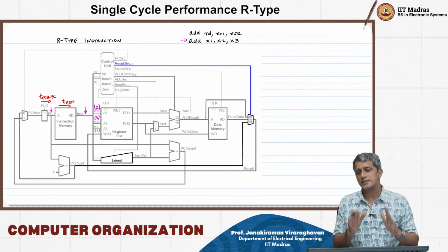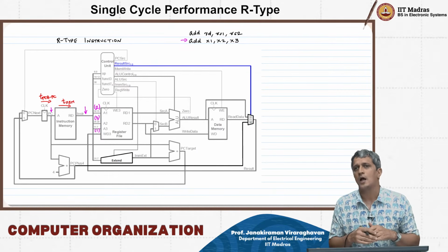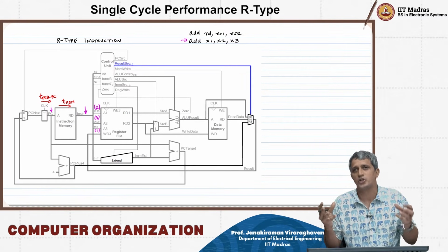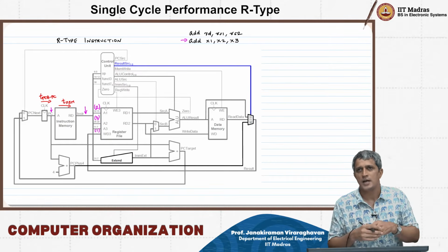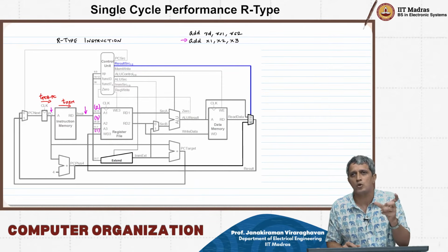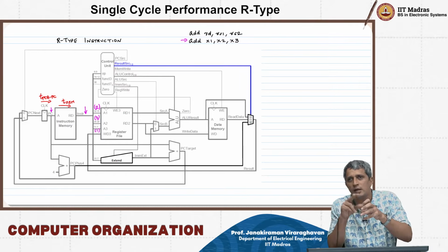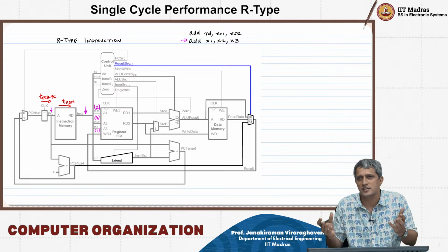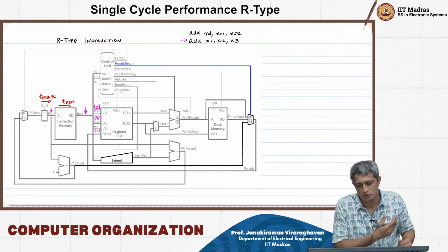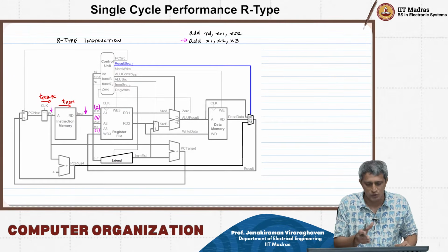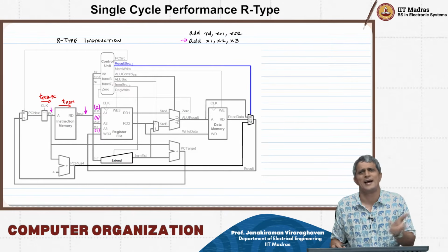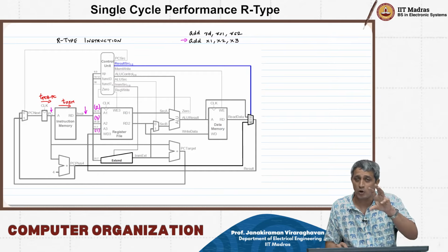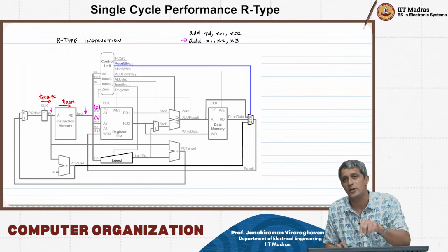Now this is a good point to highlight the nice instruction structure of the RISC-V processor, right? It's not that, for example, you had to go through the decoder and then figure out what the registers are and so on. The register address is available directly, you just feed it straight away into this register file and then you get it, right? Otherwise you have to go through a decoder, then get the register address and then feed it to the register file.